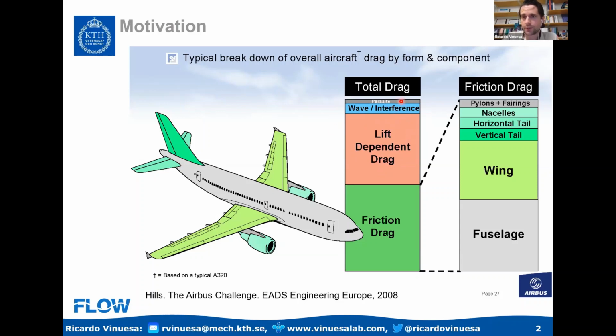The lift-induced component arises from finite wings due to the pressure difference between the pressure and suction side, where wingtip vortices are formed with a quite important effect on the capacity of the wing to extract lift from the flow. So looking at turbulent boundary layers around wings helps us to understand around 90% of the total drag in aircraft.